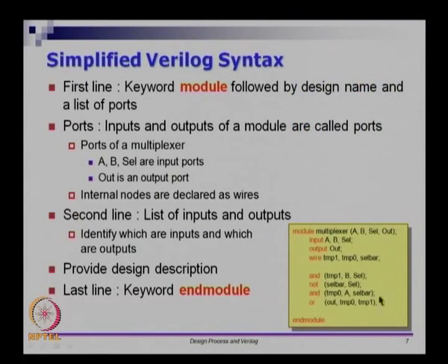You see this thing in the right bottom here, that is the description of a multiplexer done using Verilog. The first line starts with module and the last line ends with endmodule. Whatever you see in red here are keywords, meaning these are words used in the language which you cannot use as a variable. So you have module, endmodule, and in this case we are designing a 2:1 multiplexer, so I am calling that multiplexer. Module followed by the module name, multiplexer.